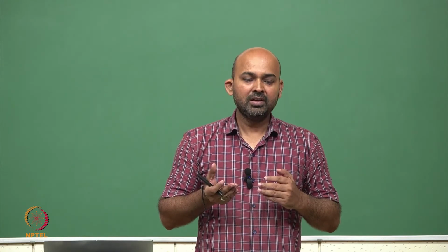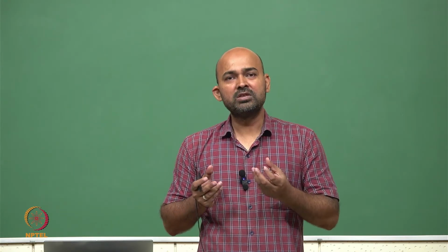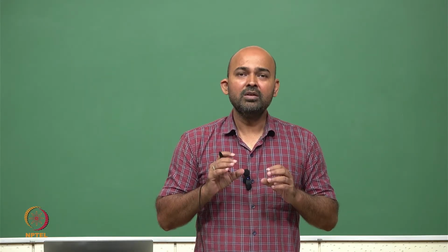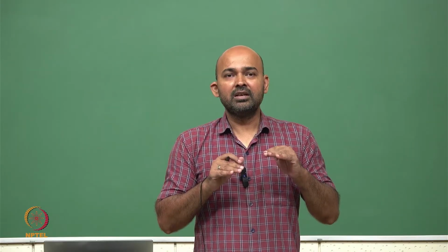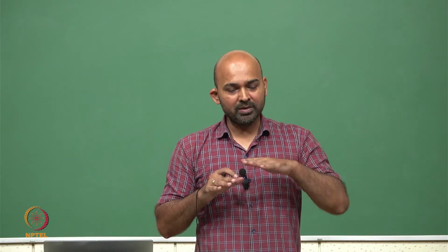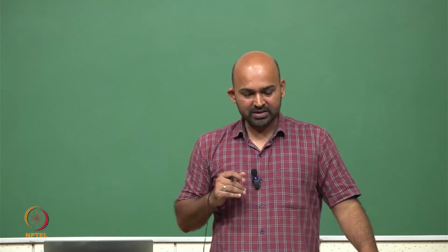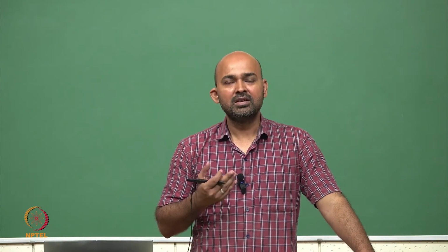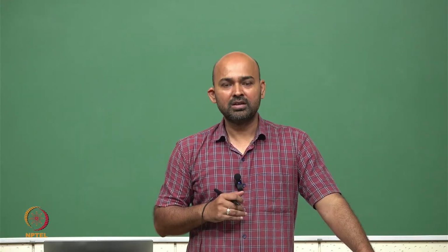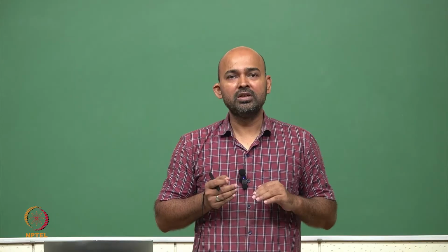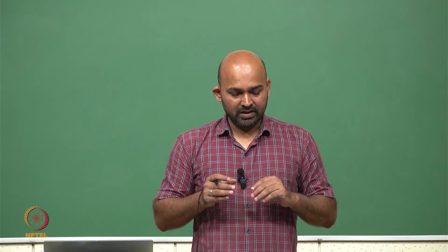So this is okay for very small circuits where we have only 2, 3 or 5 components. However, we need to note that if it is a planar circuit, you can represent it in a plane, then you can put it on a single layer PCB. The cost wise it is very cheap compared to the other options. So only one surface we are putting all these traces and components together.